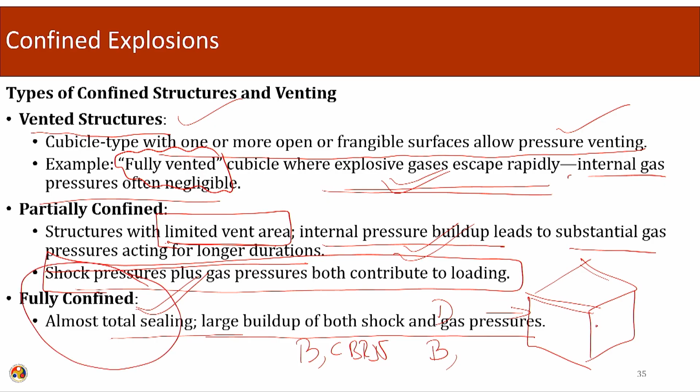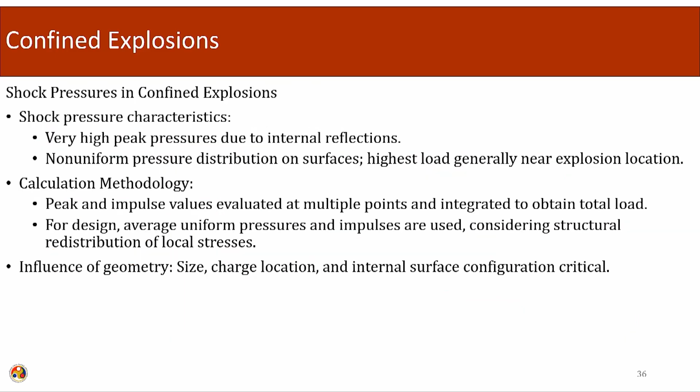Due to the nature of the accumulation of the pressure, the shock pressure and the buildup of the gas pressure, this structure needs to be designed properly to account for this large accumulation of the pressure, even though the threat level can be from a minimal amount of charge. Due to the accumulation, the design requirement becomes stringent. So, the fully confined structure has to be designed properly. This becomes a big challenge in the structural design.